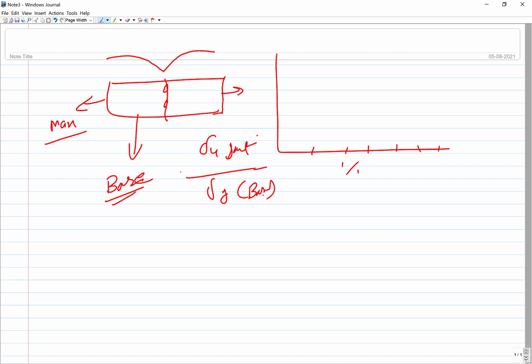This ratio is used to determine the joint efficiency. Obviously if there are pores, impurities or limited bonding in the diffusion bond, then the ultimate strength is going to be lesser than the base metal, and it may be like 70%, 80%, or 90%. So in general, increasing the percentage of pores or discontinuities at the interface reduces the strength of the joint.